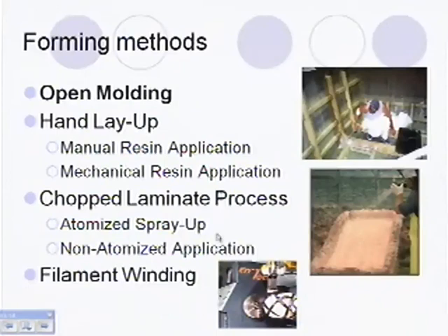And then on the bottom we have filament winding. This is kind of an unusual one. It's mostly used for making tanks, like high pressure tanks and things like that. Basically it has a spool that spins, and then it feeds out the carbon fiber braid or weave onto it, and it moves back and forth and just wraps the whole thing in carbon fiber. This applies tension to it, so it's molding this tank under tension, which is going to give it greater strength and greater rigidity.